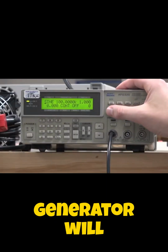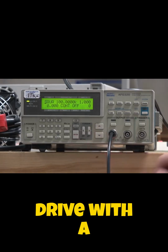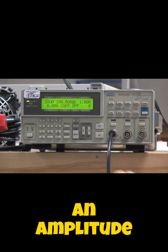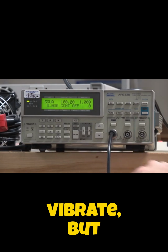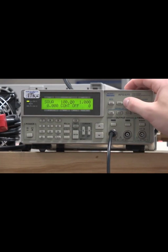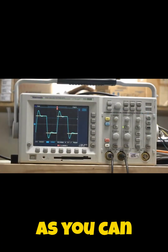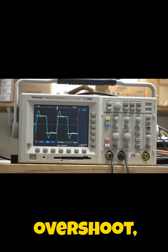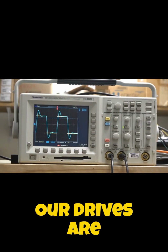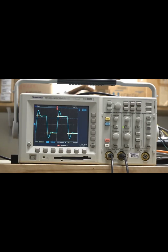The signal generator will serve as the command source to the drive. We want to provide the drive with a 100 Hz square wave at an amplitude of 1 volt. This will cause the motor to vibrate, but stay in one position. As you can see, this is what our current response looks like prior to tuning. There is a large overshoot which then levels off. Our drives are shipped with a high default current loop integrator value, so we will focus on decreasing this gain.